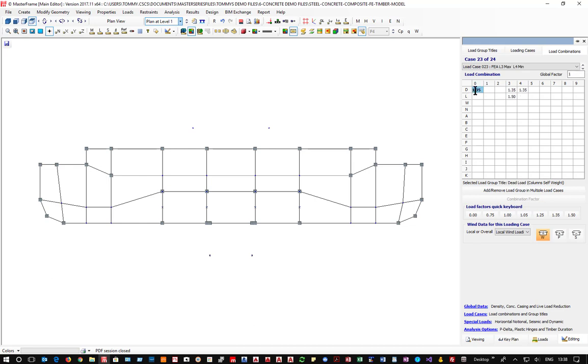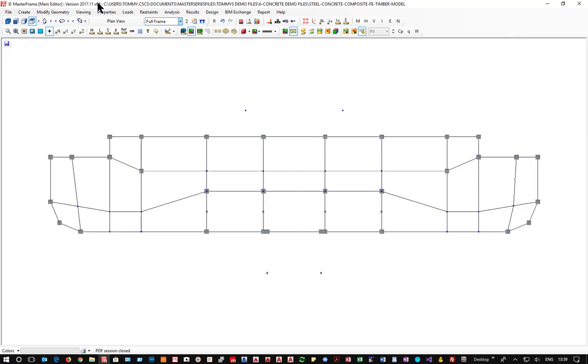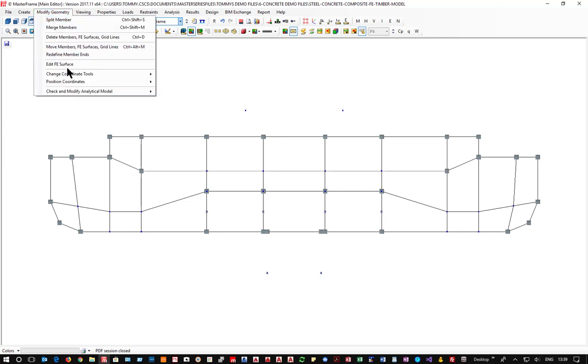The D1 is basically to do with the self weight of the slab, and the D1, 2, 3 and 4 are for additional dead loads. So the D0 is basically your self weights, and it says self weight in here, so that's what we would use that for normally. So that allows us to do the patterning very, very simply. Now the FEA is again very easily set up.